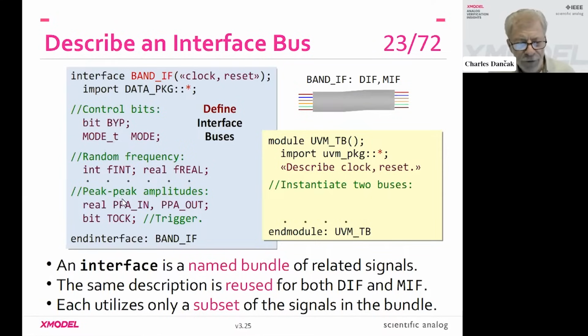Here's the interface definition. Notice we're reusing the same interface bus both on the driver side and monitor side. Each will emphasize a different subset of the signals. And we're importing data package where we define the mode type, and then we have access to all these signals.